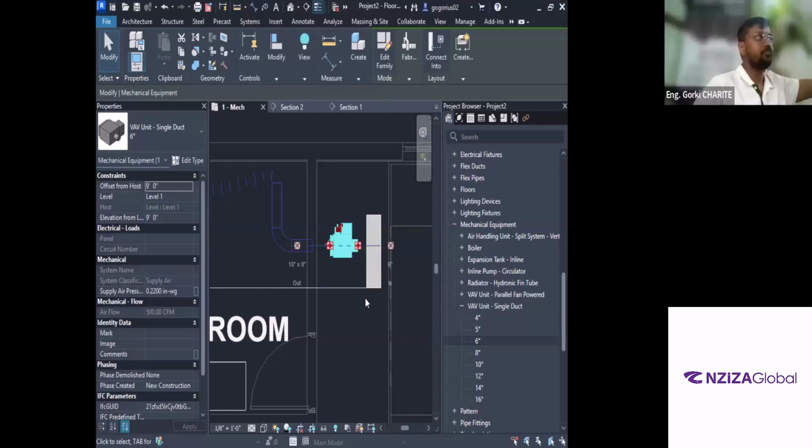Now, as I was saying, whenever working in Revit, have minimum 2 views on, floor plan and section. If you want to have more views on, that is fine. Section, horizontal, vertical, the 3D selection box that I have shown, use that as well. Why are we using that? Let's go to this section view and try to see what is going on over here. The thing is, the duct is over here. I'll talk about why the duct is showing as one line only. But our VAV box is on top over here. The alignment.